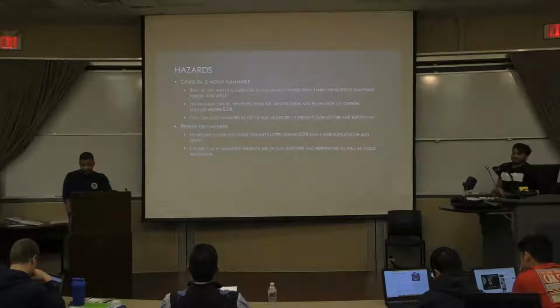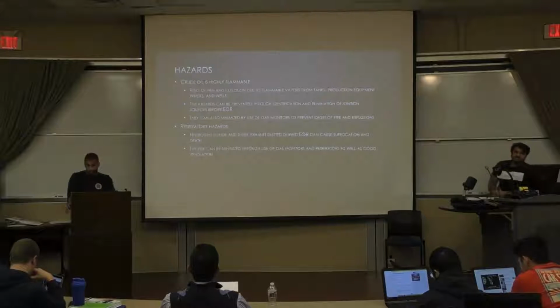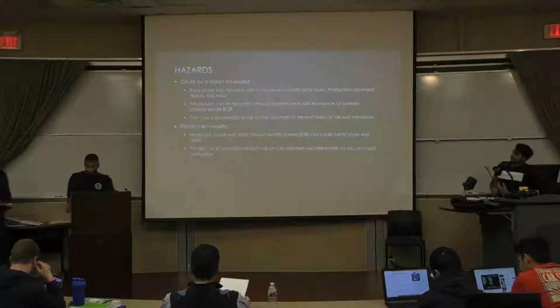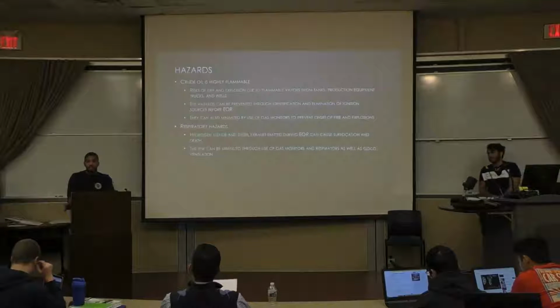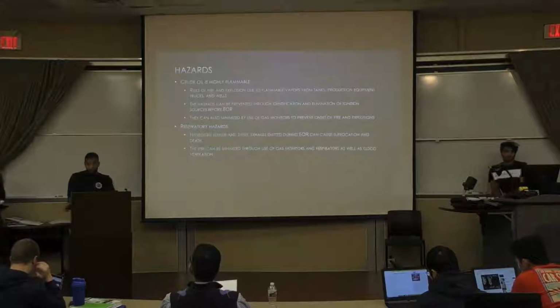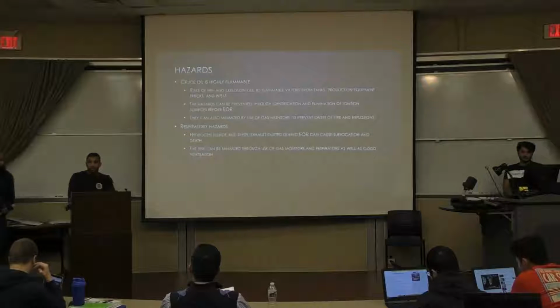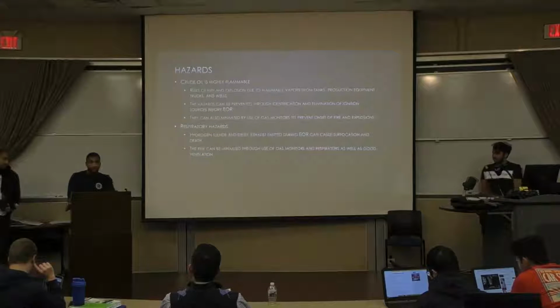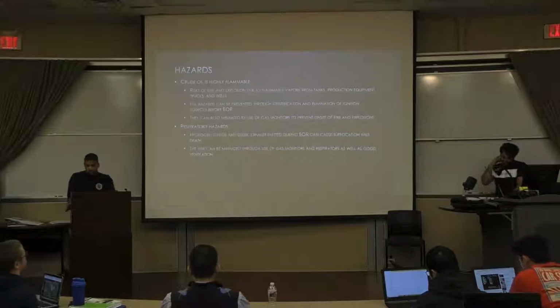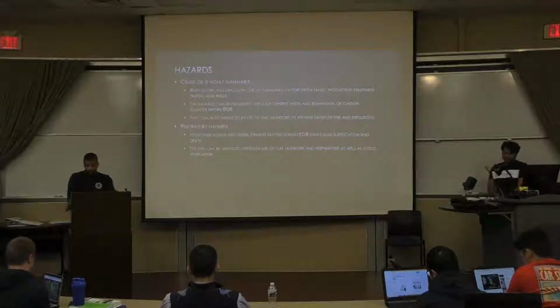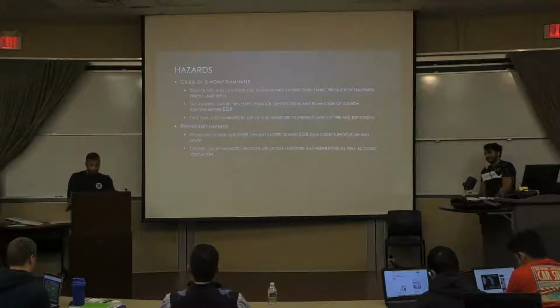Moreover, carbon dioxide injection EOR is highly hazardous. There are high risks of fires and explosions due to the flammable vapors from tanks, production equipment, trucks, and wells. However, identification and elimination of ignition sources prior to the process can greatly reduce the hazards. Gas monitors can also be used to prevent the onset of fires and explosions.